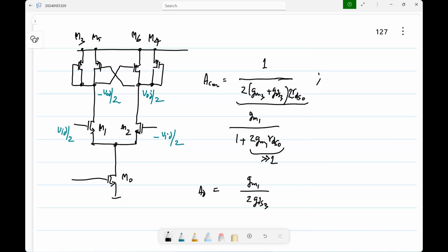Is the idea clear? So now we will make fully differential circuits, of course. Fully differential circuits we can analyze using common mode and differential half circuits. You get the advantages of fully differential circuits only if the two sides are varying in equal and opposite manner. That means everywhere you should have differential signals, but no common mode signals. Of course, it's not possible to have zero common mode signals; you would like to have it as small as possible.